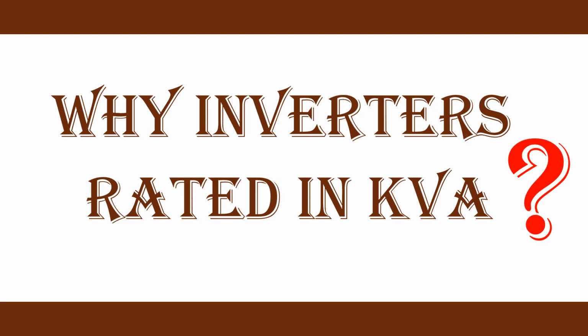The inverters are rated in kVA because the inverter doesn't know exactly what is the power factor of the connected load. Or in other words, we can connect any load with any power factor at the inverter output such that the output current should not exceed the maximum permissible value. Now, let me explain everything in detail.